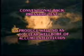The well should be produced into a pipeline long enough at a high enough flow rate so as to clear the well bore of accumulated fluids prior to initial shut-in. If the well bore is not cleared of fluids, the well may be blown to atmosphere. If no pipeline exists, the well may be blown to atmosphere or flared to remove liquids. The well is then shut in until the rate of pressure buildup in a 30-minute period is less than 0.1% of the previously recorded pressure.